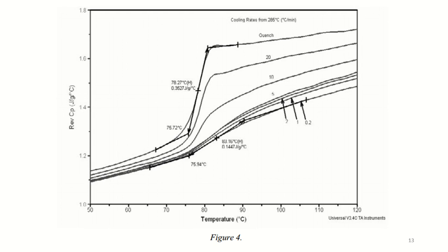Although this is a good approximation of the amorphous content of the sample, the actual content is probably slightly higher. We can use a formula: percentage amorphous phase equals 0.14 over 0.35 times 100, which is equal to 40% amorphous phase.